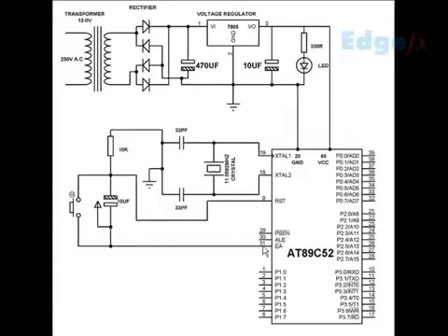And pin number 31 is to be held high. That means this is connected to positive. Pin number 31 is held high always. That is for the purpose that, if we wish to program it while it is in the circuit, then this particular pin will be used. Since we are programming it externally, when we take it out, program it and bring it back, this pin, as per the manufacturer's data sheet, is required to be connected to the positive point. So pin number 31 is connected to the positive point. So these are the standard connections.